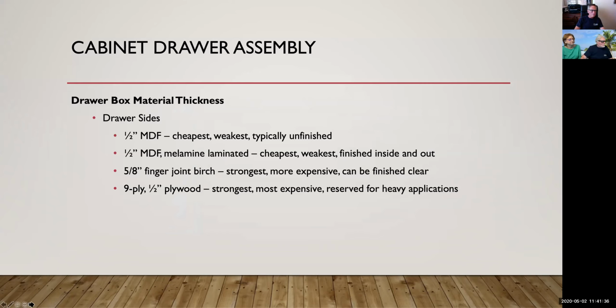Cabinet door hinges: we grew up in a home our grandfather built at the turn of the century, and those old cabinets had surface mount hinges. We find that in many of the projects that we're doing, we replace the surface mounted hinge with a concealed hinge, because the surface mounted hinge has very limited adjustability. It is, however, the least expensive alternative, but it also happens to be the least popular.